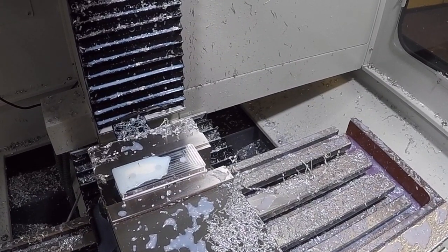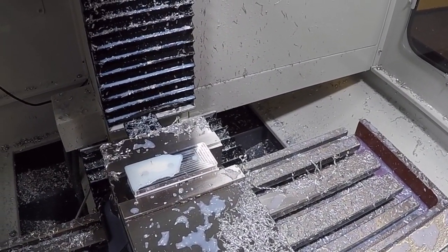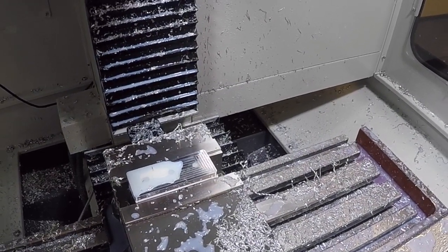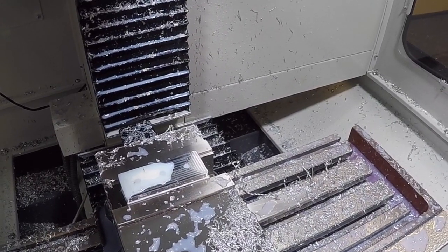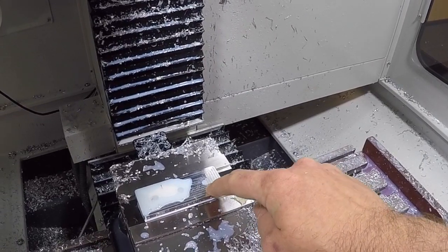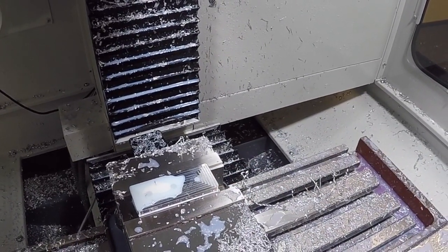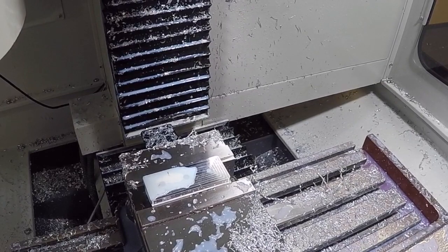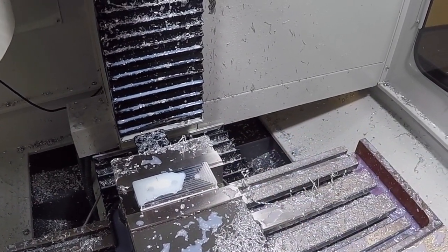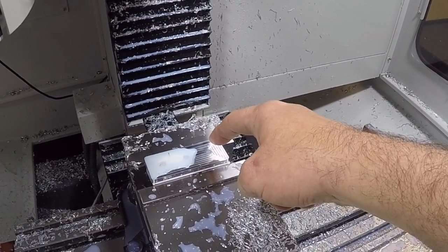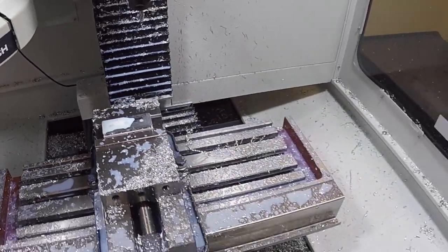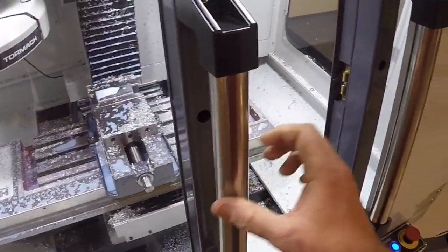Here's where we are on our part right now. We have done 3 operations. That would be drilling the clearance holes, and then we switched over to a 1/4 inch 3-flute end mill. With that 3-flute end mill, we faced it. You can see we have a nice surface finish on the top here. Then we made a profile around the perimeter with a 0.1 inch radius on the end. Our next step is to make a slot over here and a slot over here using our entry points that we've made already. I've already set that up.